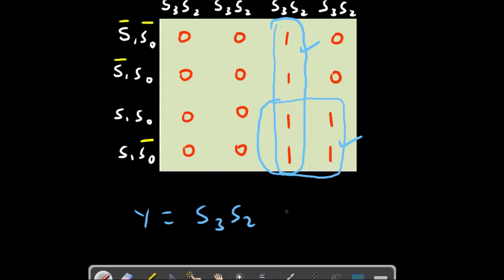So this is an SOP, and we need to apply this particular logic so that whenever there is a digit which goes beyond 9, we need to add 0110, that is BCD 6. So this is the SOP K-map, and we get this particular equation.